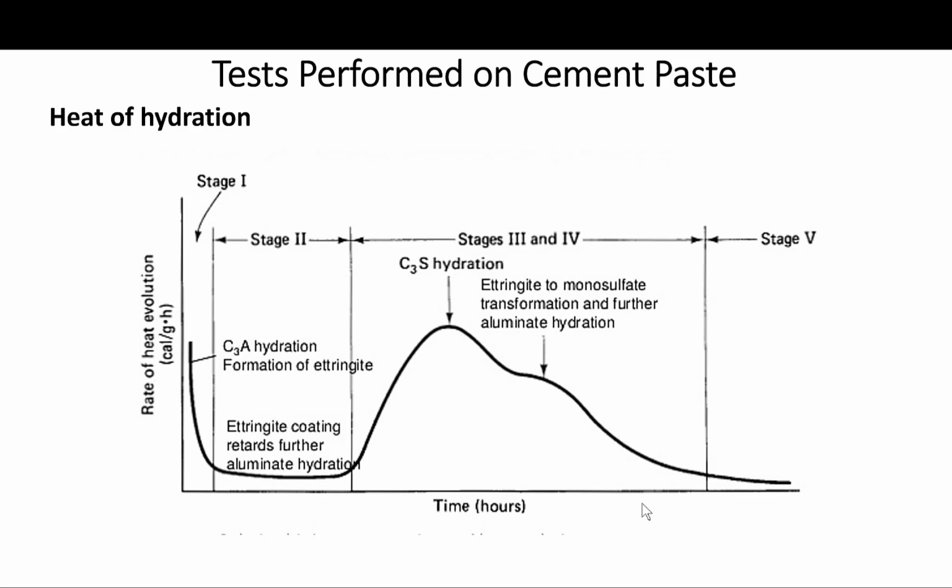Using this technique has great advantages. In the concrete industry, it can be used to determine the total heat, setting behavior, and quantifying retardation and acceleration, where these peaks happen as compared to one situation to another. By this we optimize the calcium sulfate addition. If you remember, I just talked about the flash set, the quick set, and how to properly sulfate the cement.